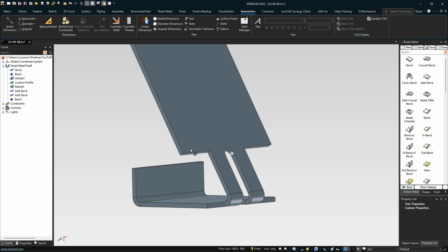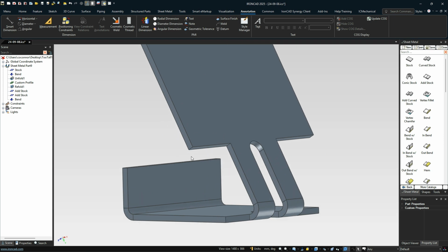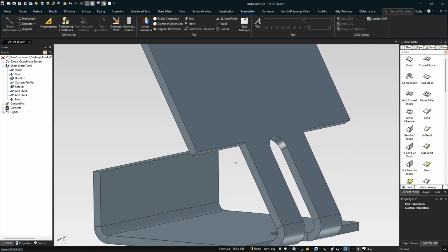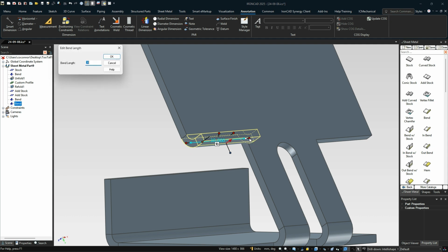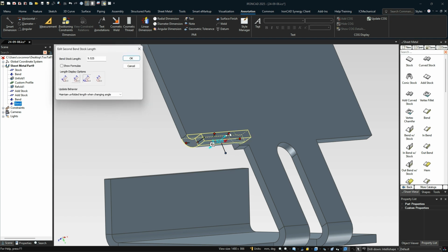We're going to add another tab here. So let's go ahead and do this one. In this case, it's going to bend up, and we need to have an outbend because we need to maintain this distance. So we'll drop an outbend here, right on the center as well. And we know the overall width of this is going to be 25. So if we double click this handle here for our width, it's set to 35. Let's set it to 25. And we know the distance from the top on this guy, setting from the back sharp there, is going to be 30 for that.